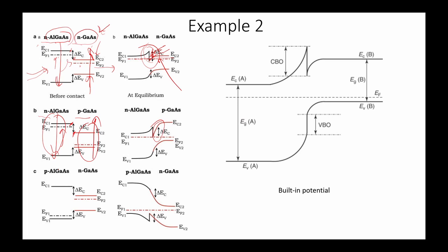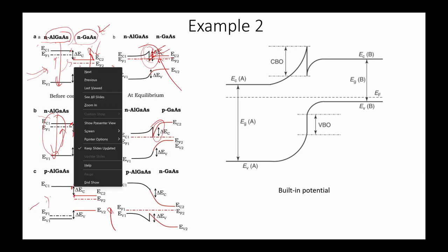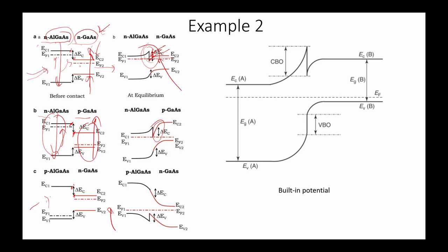And this is another different case. You can easily draw the band diagram of any type of heterostructure if you know the basic rules. The two basic rules: first, align the Fermi level; second, fix these 2 points at the conduction band. Just fix these 2 points and you are done.